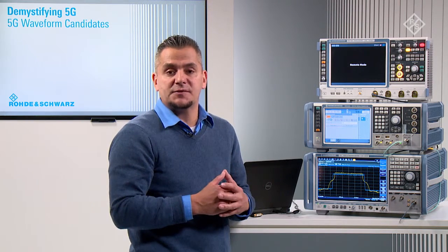Well, if there are power amplifier design companies out there that want to make sure that their amplifiers also support these kinds of new waveform schemes that are being discussed right now in the industry, they could utilize this setup. They could utilize the signal generator to generate these signals, to play with the parameterization, probably a little bit better than I did. And then of course use the analyzer to do power amplifier specific measurements, measure AM to AM, AM to PM curves, measure the CCDF to get a sense of the crest factor, the peak to average power ratio, and all these kinds of things.